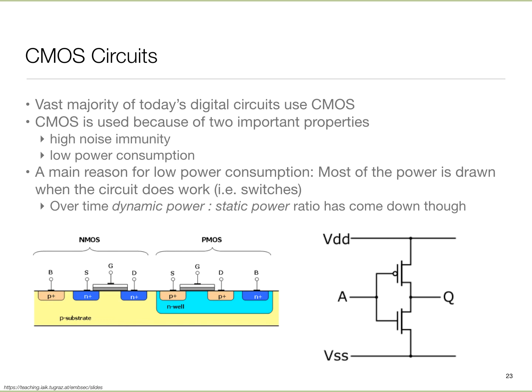They're complementary. So, for example, this switch is open, as in disconnected, if the voltage is low, and it's shorted if the voltage is high, and this guy acts exactly the opposite. So, in a very idealized sense, these are switches that have complementary behavior, and they're controlled by the input, and then you have the power supply here, and you have your ground output.